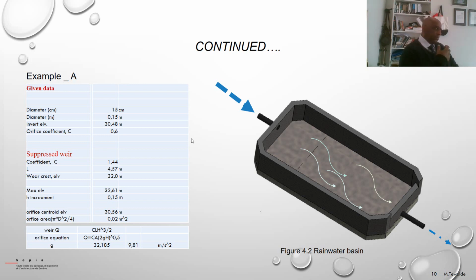In this we need to know time of concentration, lag time, and so on: infiltration, detention, evaporation. All these things are considered to calculate the hydrograph or the runoff volume. And another method to calculate the peak discharge is the rational formula, that is for small catchments, I think.